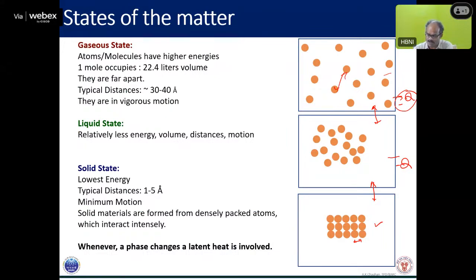It remains there, and so the atoms which were supposed to have minimum energy when they go to the perfect lattice sites already have a lot of energy, and before they release that extra energy, they become fixed, and therefore they go into the amorphous phase. So it is very difficult to grow crystals of oxide materials which have poor thermal conductivity as compared to the metals.